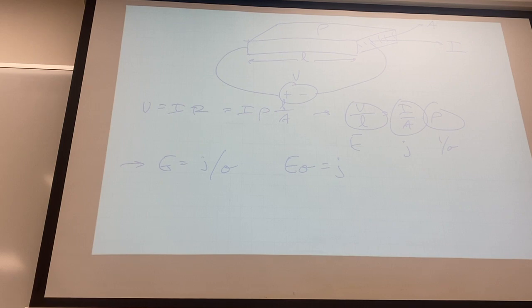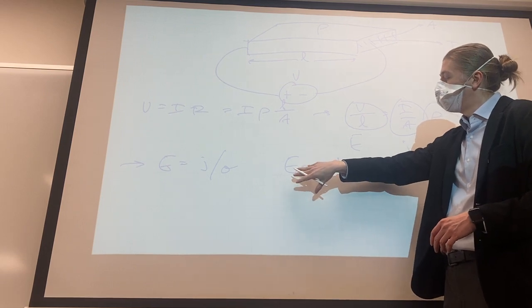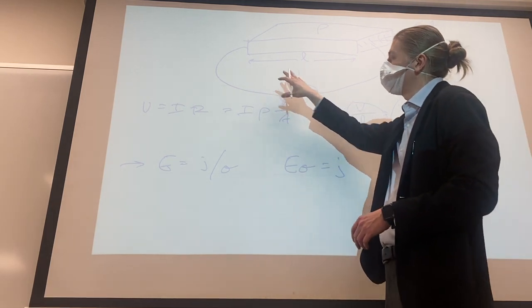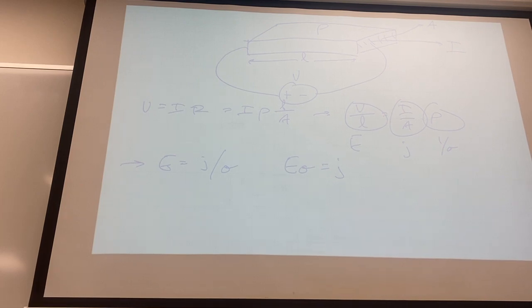So we're back to the expression we just wrote on the last slide, just moving Ohm's law around in order to be in units of, or with respect to, all the stuff that we know how to calculate about semiconductor states instead of things that we're applying and overall resistances and overall currents. We can take all the stuff that we're looking at the lowest levels, figure out how many charge carriers exist, figure out where the mobility is, and build up how the device should behave in a circuit from there in response to what we know about Ohm's law.